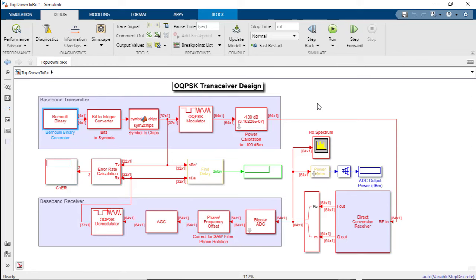If you want to enhance performance in the model, you would look for those fastest running blocks, the red ones, and go there. You also see the signal dimensions going into and out of each block. That's very, very convenient as well. Oftentimes, errors can occur with incorrect signal dimensions, and it's very easy to see where those errors might happen through this visualization. Also I'd want to draw your attention to the different domains that are represented in this model.